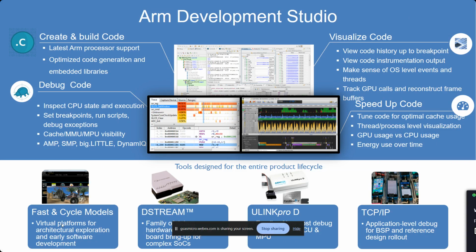Once your hardware is ready, you can use the JTAG DStream-ST debugger, load the code to the board, and do real-time debugging. If it is lower end, you can use the Keil ULINKpro debugger, like that.